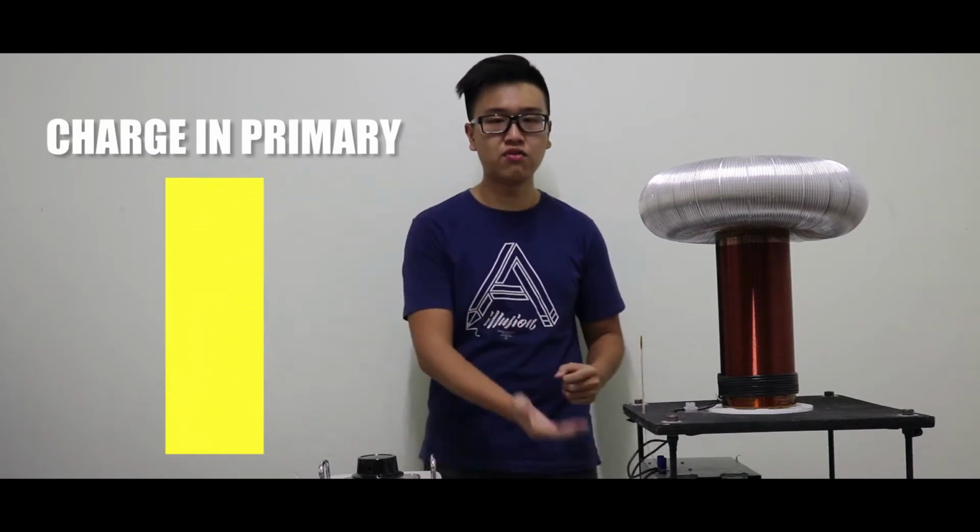A Tesla coil would consist of two parts, the primary coil and secondary coil, each of them having their own capacitors. The two coils and capacitors are connected indirectly through electromagnetic induction. Furthermore, a Tesla coil will need a high voltage power source in order to properly work. When the power source is hooked up to the primary coil through a transformer, charge begins to build up in the primary capacitor. Over time, this charge gets so large that the current flows out of the capacitor into the primary coil, creating an alternating magnetic field.